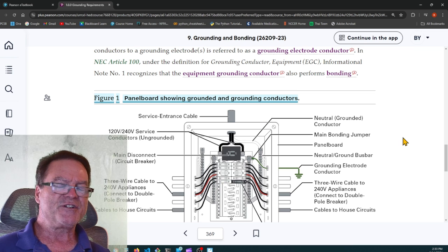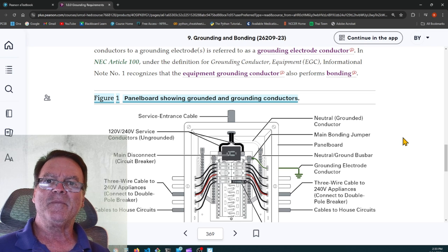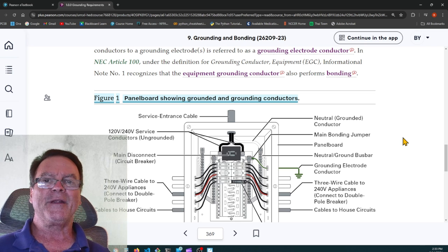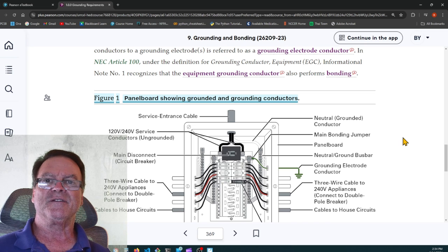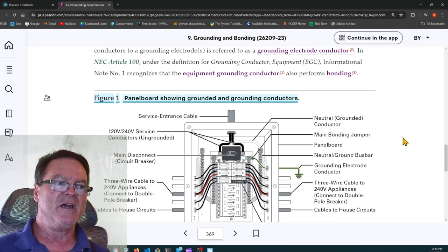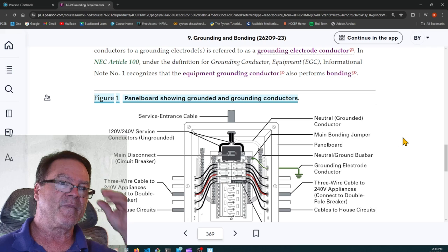If you have two pieces of machinery in the same room and they're metal, you take a wire between them, connect them together, you've just bonded them together. If you take a wire and extend it to the earth, to ground, or to some wire in place of the ground, or that extends eventually to ground, you've grounded that system or that equipment.